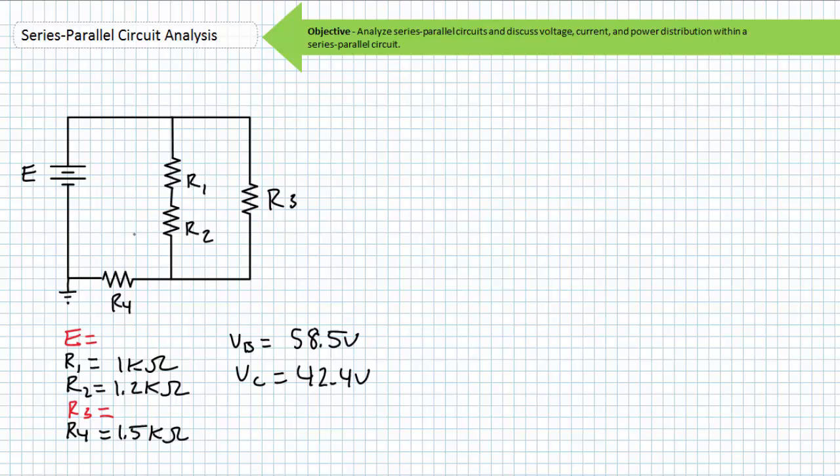Voltage across paths in parallel will be the same. For every rise there is a drop, and what goes in must come out. I'll start by assigning some nodes. Node A is the junction of the top of R1 and R3 and our source. Source current should split here. Node B is the junction of the bottom of R1 and the top of R2.